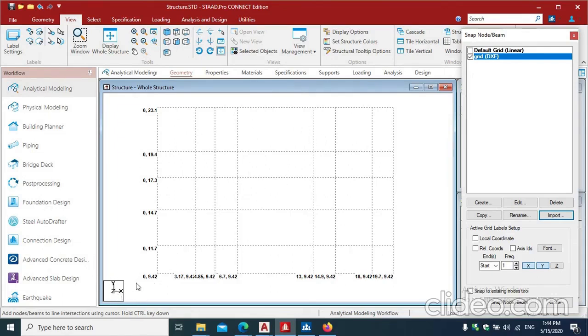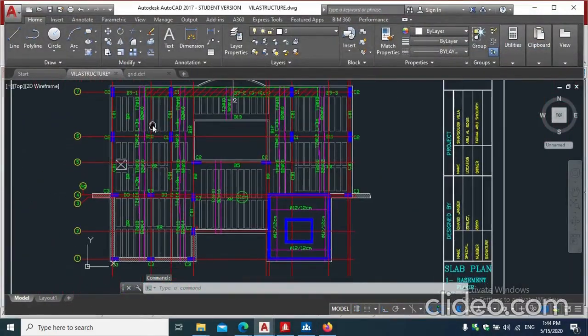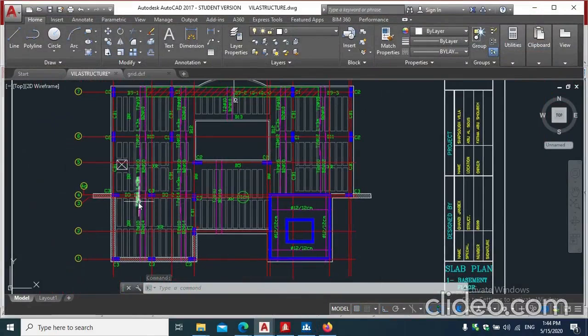An important point here before you start drawing on this grid is to notice that it's on the x and y axis in the plan XY. If you took this grid from Autocad to draw a plan like this, the plan in STAAD must have the y as the gravity direction. Therefore, your plan, like the top view of this node, must be an XZ so that Y comes out of the screen, which is the gravity direction.